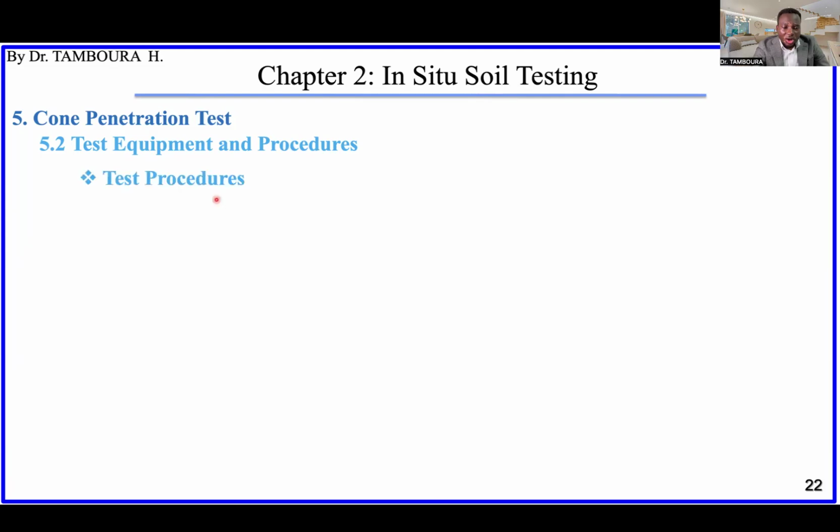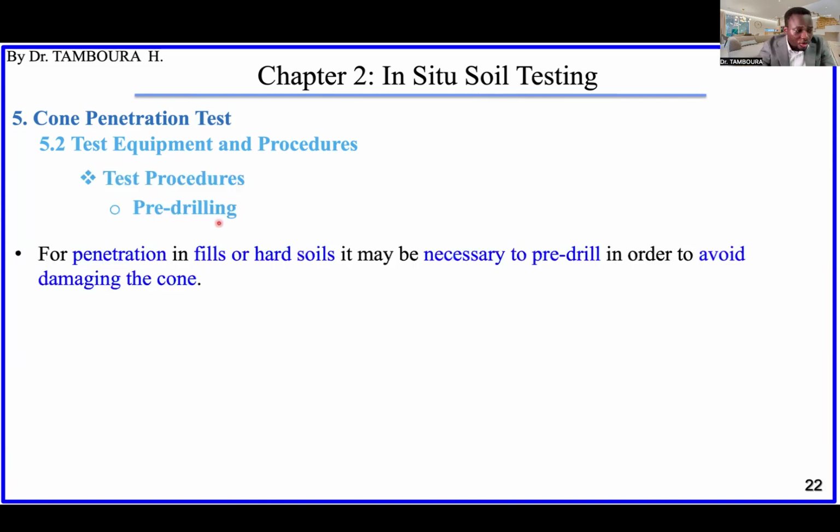Now, how is the test performed? How do we perform the test itself? In some conditions, for penetration in fill or hard soil, it may be necessary to do pre-drilling in order to avoid damaging the cone.